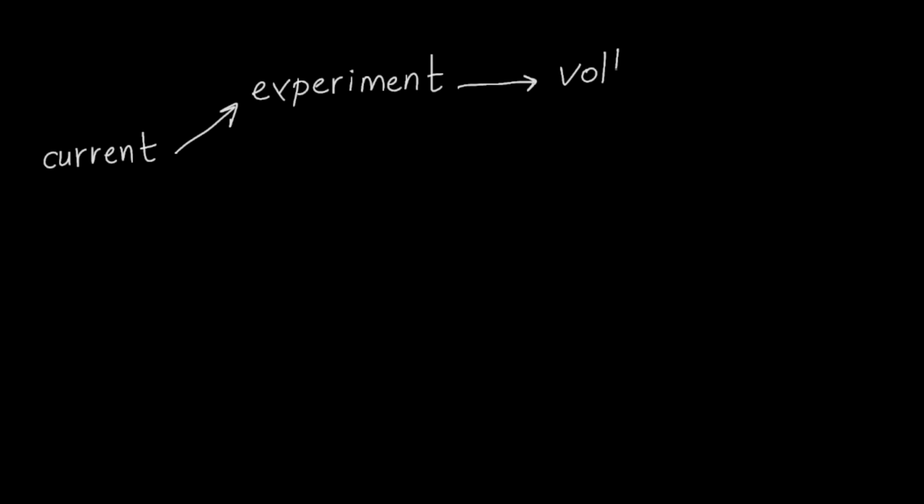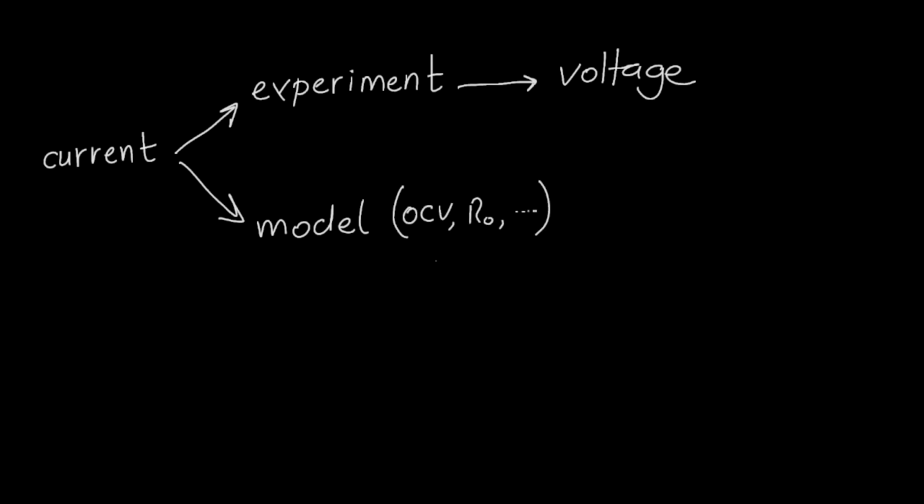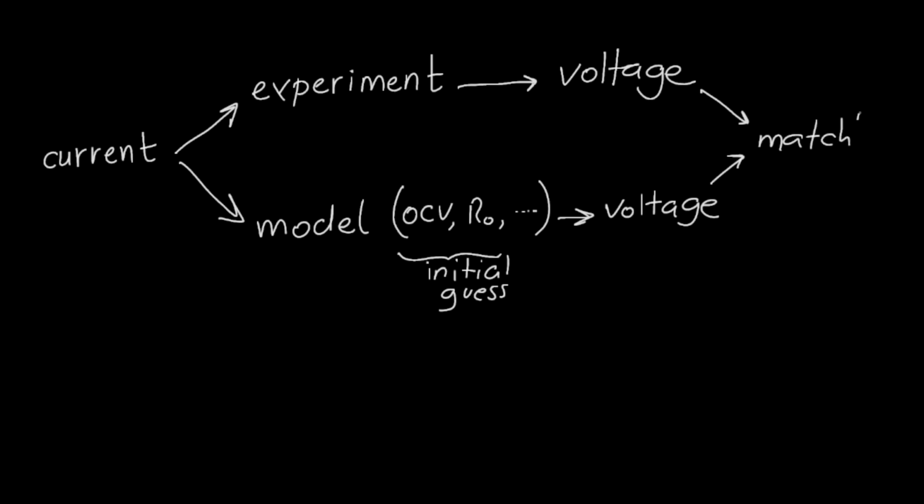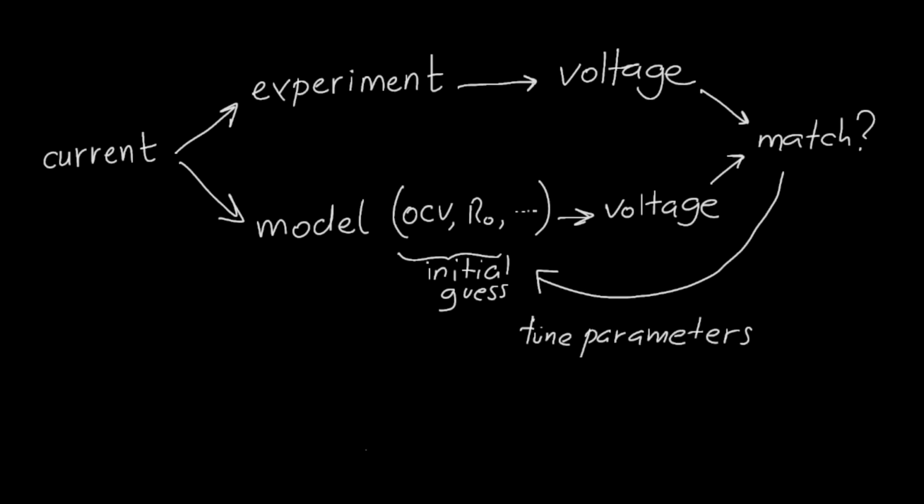A second way would be to simulate the experiment with an initial guess of the parameters, compare the simulation results against the experimental measurement, and modify the parameter values to improve the fit. This is a very general method that does not require any assumptions, but it needs many simulations for convergence, because it is based on a nonlinear optimization scheme working on a large number of parameters. This is especially important for long experiments that take a long time to simulate. It also needs to be repeated for every temperature of interest. All of the above means that the entire procedure takes a few hours to complete.